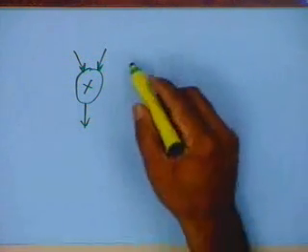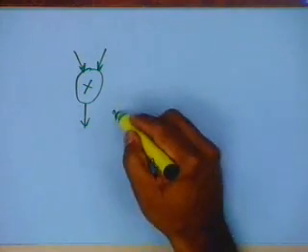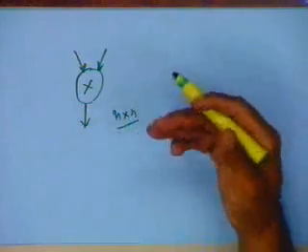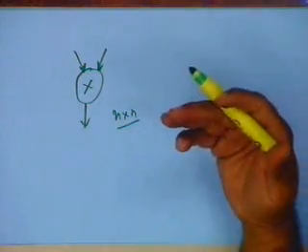There are n stages of adders or n minus 1 stages of adders for doing an n by n multiplication. If you use Booth's algorithm, or a sequential implementation, again you require so many clock pulses to do the multiplication.